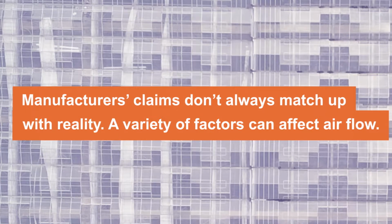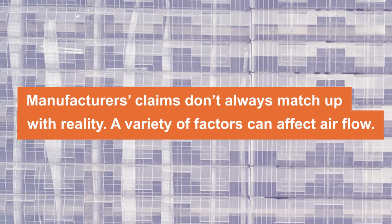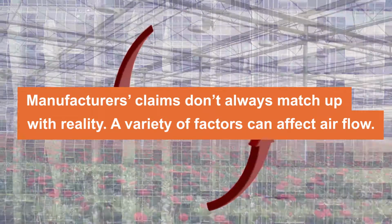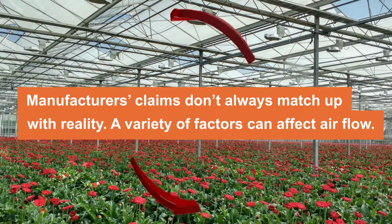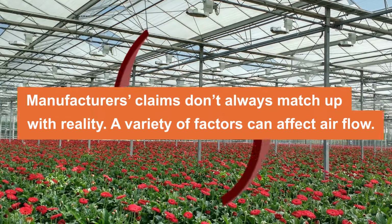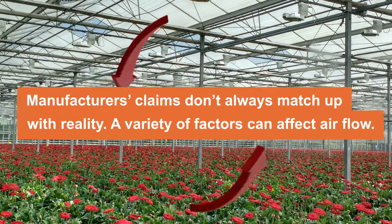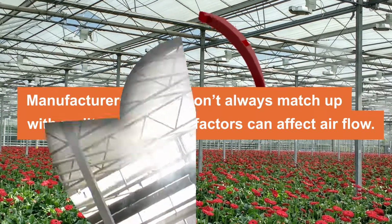The theory of where air should go based on a particular layout or manufacturer's claims does not always match up with reality. Factors such as wind direction or the slope of a glasshouse can significantly affect the airflow. It can be a good idea, therefore, to visualize how the air is moving. One effective method is a smoke test.